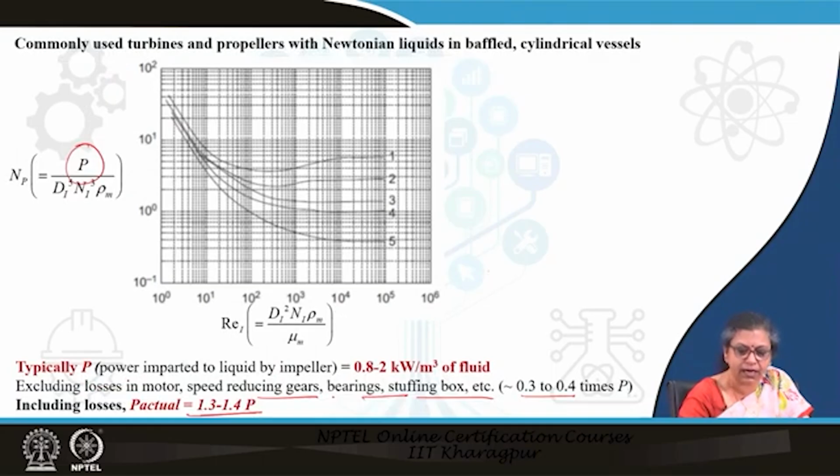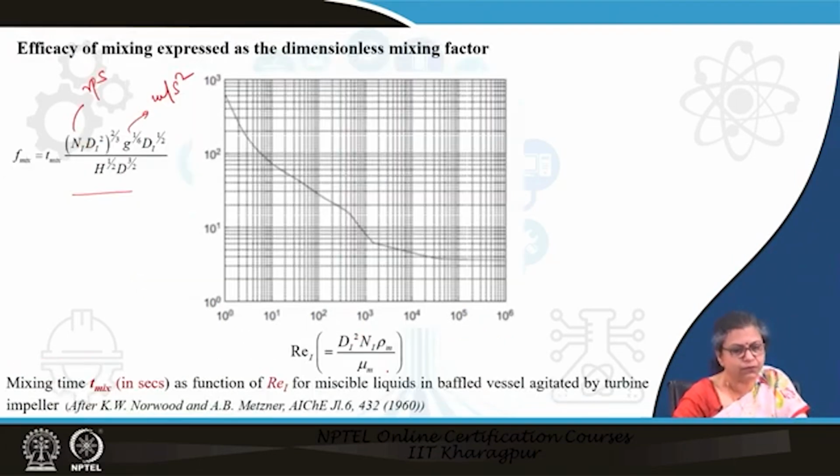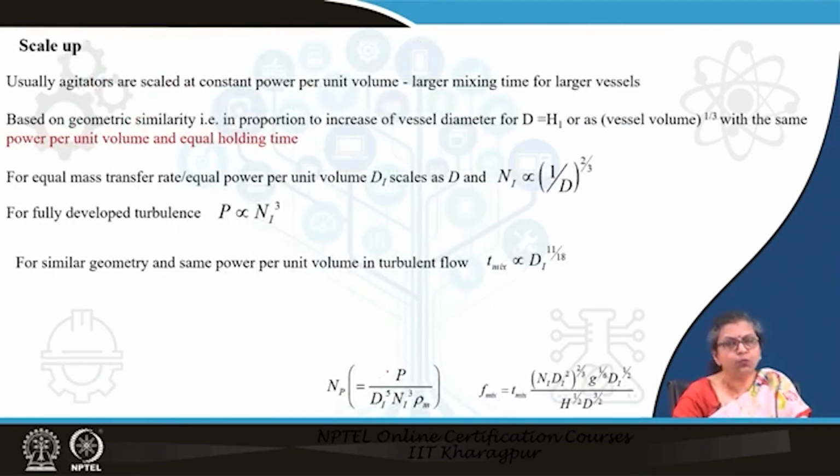One thing regarding the power, I forgot to mention: after you have calculated the power, it is important to remember certain checks which we do for all designs. So, check whether the power more or less conforms to this particular value or not. Once we have selected the vessel, designed the impeller, and calculated the power,